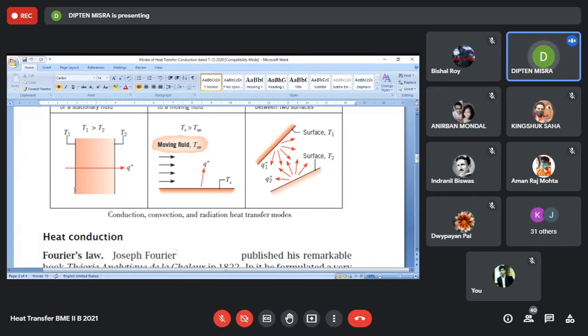Here also, a similar approach we can adopt, that the flow of energy known as heat energy can be given by the ratio of the potential difference for heat flow, that is the temperature difference, to a resistance. Heat flows because of a cause, that is the temperature difference. So the rate of heat flow will be equal to the temperature difference divided by a thermal resistance.